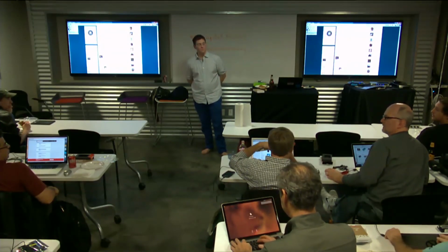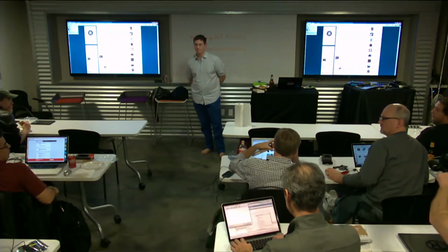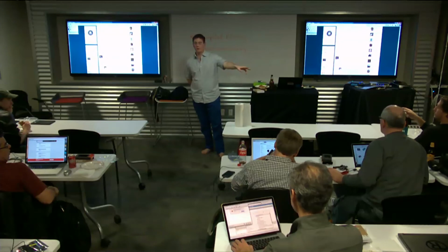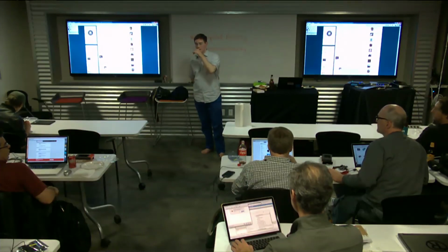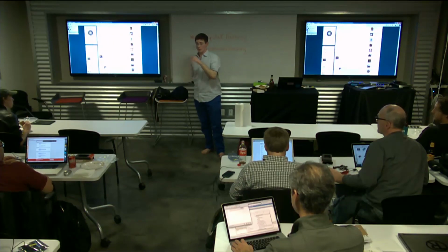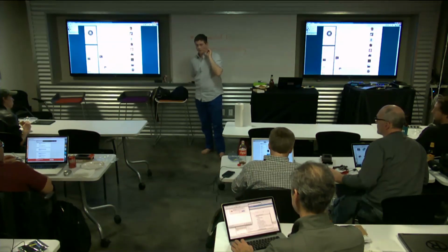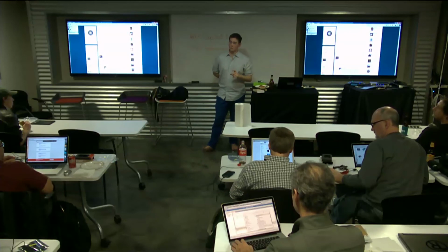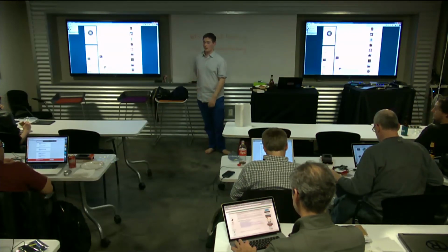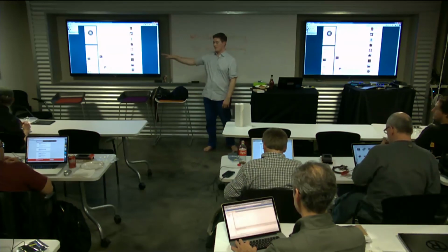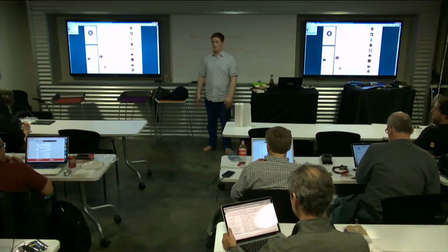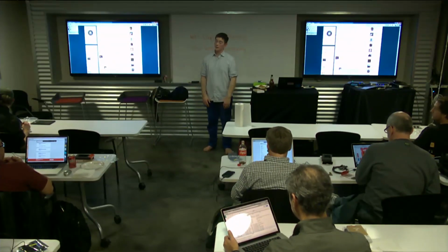Yeah, so there's particular Nordic kits out there that come with the dongle, the sniffer that plugs into your computer, and the other board. Beyond that, there's also cheap BTLE, like $5, $10 dongles from China. But at that point, you will be running on your computer. I need to figure out how to do it on the computer because that involves some tools like Wireshark and gets kind of buggy. I was probably just going to use it on a phone and be like, hey, look, the Nordic kit. It can see all the BLE devices around you. Change your name, it shows up. Give me a little bit and I'll see if I can figure out something for you.